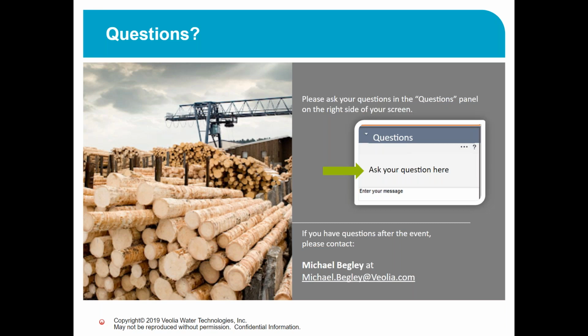So just to repeat the question, what would be the first step in reviewing to see if it would work to incorporate one of these technologies in a pulp and paper facility? The first step is probably to get some data on what size the system is, what condition it's in, and what the future conditions are, so we can go through a preliminary economic analysis to see if the investment makes sense, whether it's an evaporator or if you want to add a new concentrator.